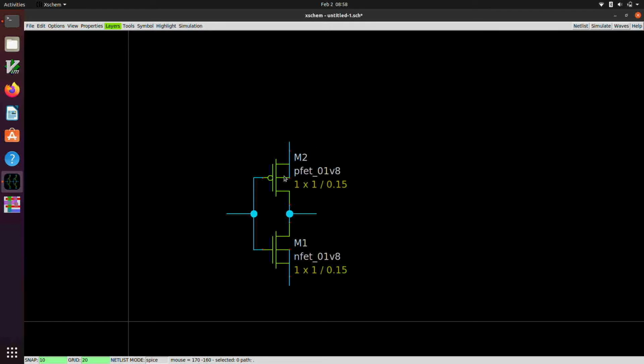The reason I'm using a 4-terminal MOSFET here and not the 3-terminal MOSFET is so that I can explicitly propagate the power supply connection into the cell via pins. It's okay to use the default bulk connections in the 3-terminal symbols.